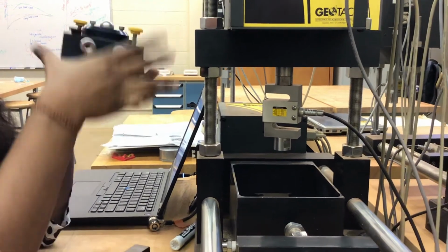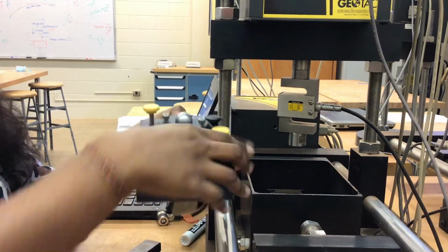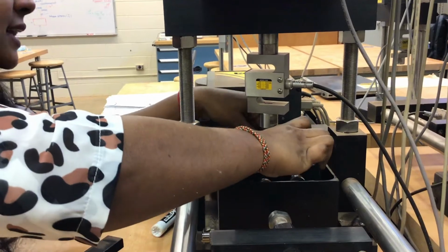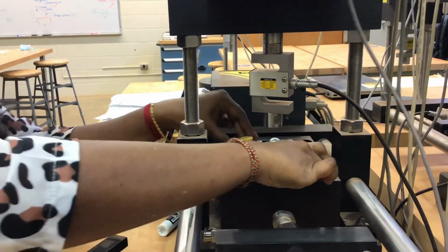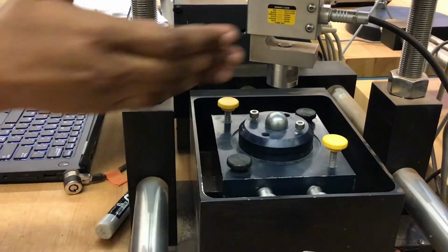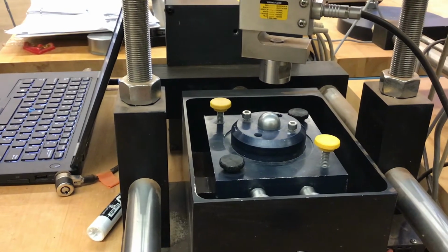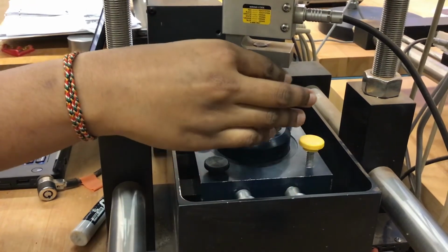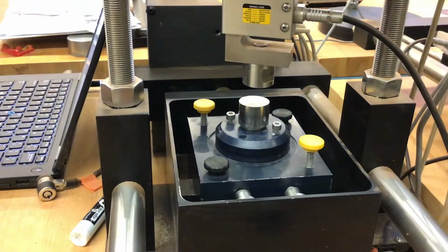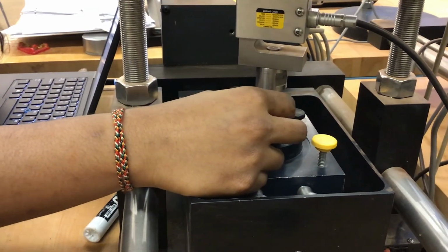Once you have calibrated your sensors and the load cells, what we are going to do now is place the shearing inside this apparatus. So make sure to place it correctly. Here we go. Now this shearing is placed, so we are going to move this one down. We are going to move this load cell down so that the distance between these two is about 1/16 of an inch. Observe it very carefully.